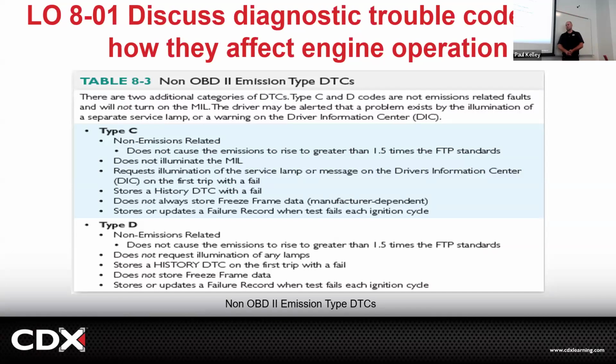How about an ignition feedback sensor to tell whether there was thorough ionization during the combustion burn? Something stupid. Some manufacturers will add an extra sensor to tell if the combustion was really thorough, but it's not necessarily tied to emissions and it's not necessarily required. It's like a system that they went above and beyond on. Sometimes the Germans will do something like that because they'll be working with Bosch and be like, hey, we're going to roll out this new system. It's really awesome. But then it's kind of like, yeah, but you didn't need to.